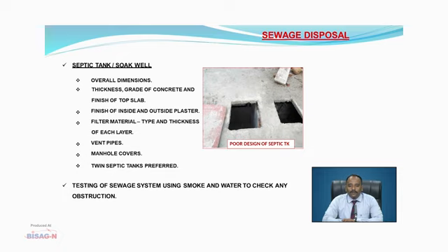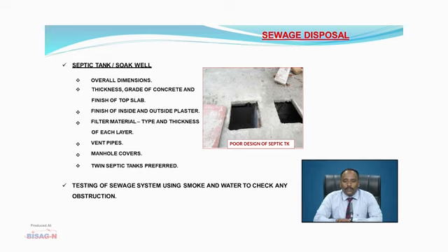The testing of sewage system has to be carried out using smoke and water to check any obstruction prior to the asset being put into use.